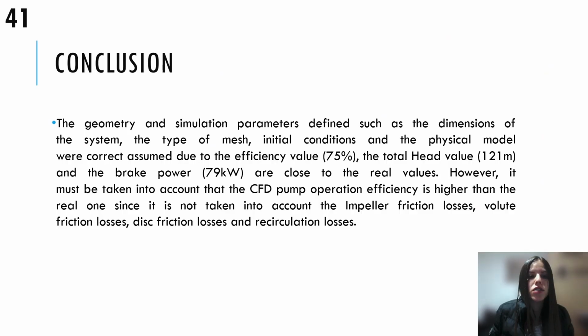In conclusion, the geometry and simulation parameters defined, such as the dimension of the system, the type of mesh, initial conditions, and the physical model, were correctly assumed, since the efficiency value, the total head value, and the brake power are close to the real values. However, it must be taken into account that the CFD pump operation efficiency is higher than the real one, since it is not taking into account the friction losses, volute friction losses, and recirculation losses.